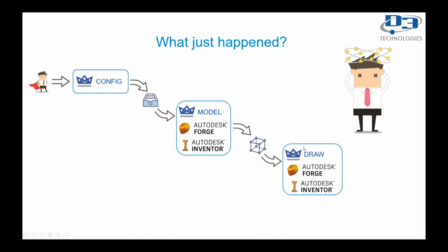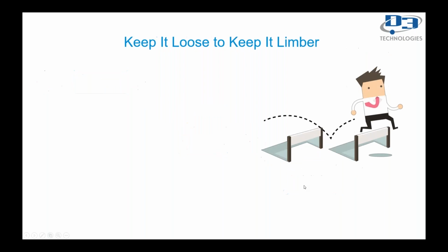And this is a simplified drawing because Forge is still in beta on the Inventor API. But some interesting things to note here is that it did this in, I don't know, less than 2 minutes. And if I send any vessel over with any number of nozzles on the head or the bottom or the side in any location, Ruler Draw will create the dimensions for them.